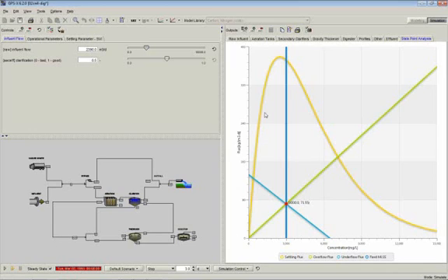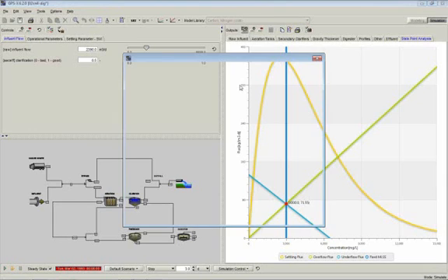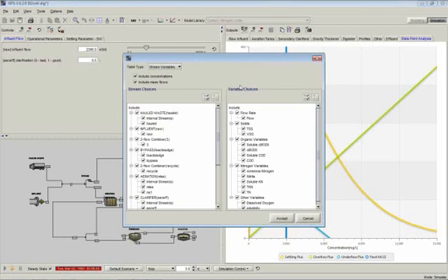Okay, so now I'm going to show you the table function, and as I mentioned, this is the one feature that we added in terms of the software that I think is the most useful right out of the box. We have a new button here at the top where you would add new tabs. So up here at the top, if you click on this new table tab, you will be prompted first of all with a list of all of the stream label connection points in your layout on the left-hand side here, and then a number of things that you can plot in a table for those connection points on the right-hand side.